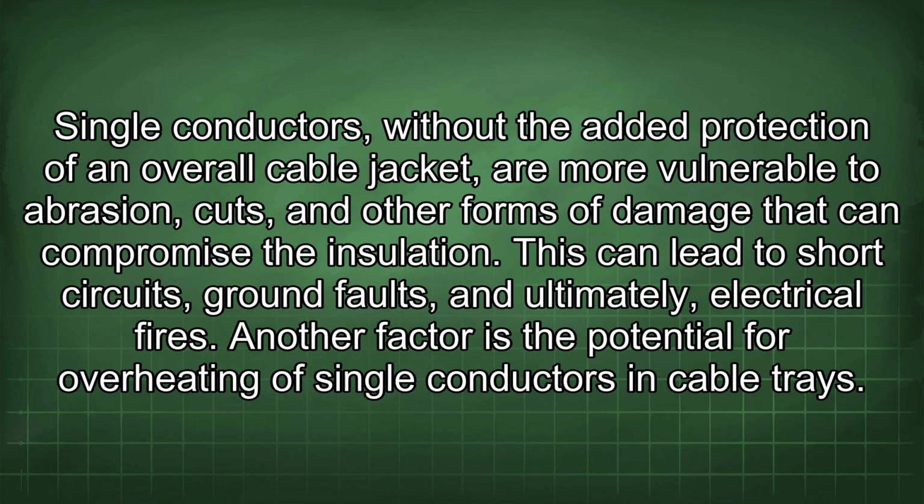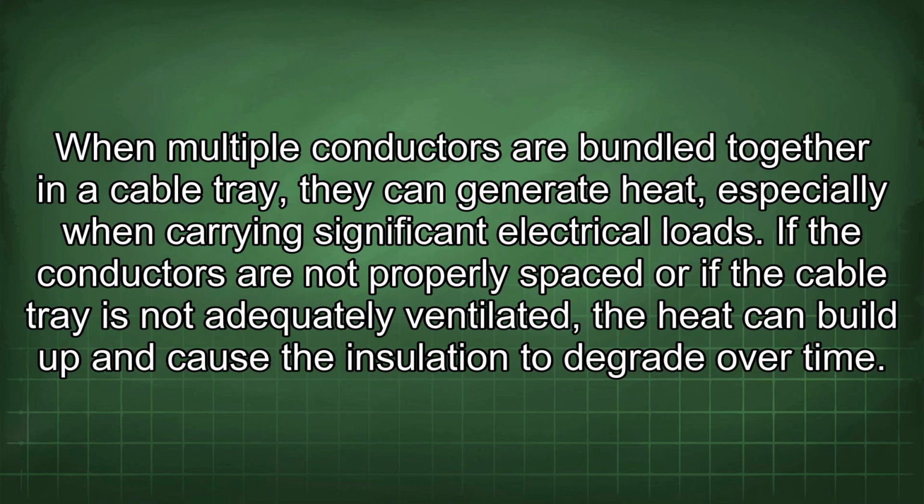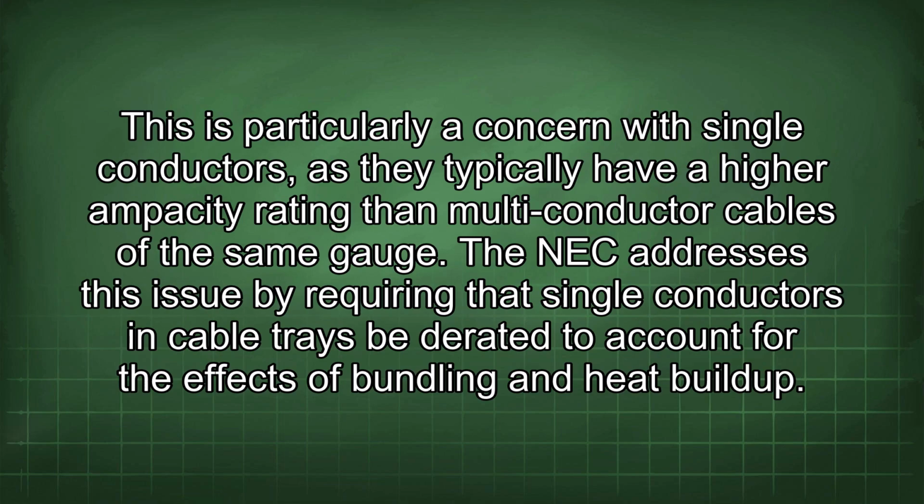This can lead to short circuits, ground faults, and ultimately, electrical fires. Another factor is the potential for overheating of single conductors in cable trays. When multiple conductors are bundled together in a cable tray, they can generate heat, especially when carrying significant electrical loads. If the conductors are not properly spaced or if the cable tray is not adequately ventilated, the heat can build up and cause the insulation to degrade over time. This is particularly a concern with single conductors, as they typically have a higher ampacity rating than multi-conductor cables of the same gauge. The NEC addresses this issue by requiring that single conductors in cable trays be derated to account for the effects of bundling and heat buildup.